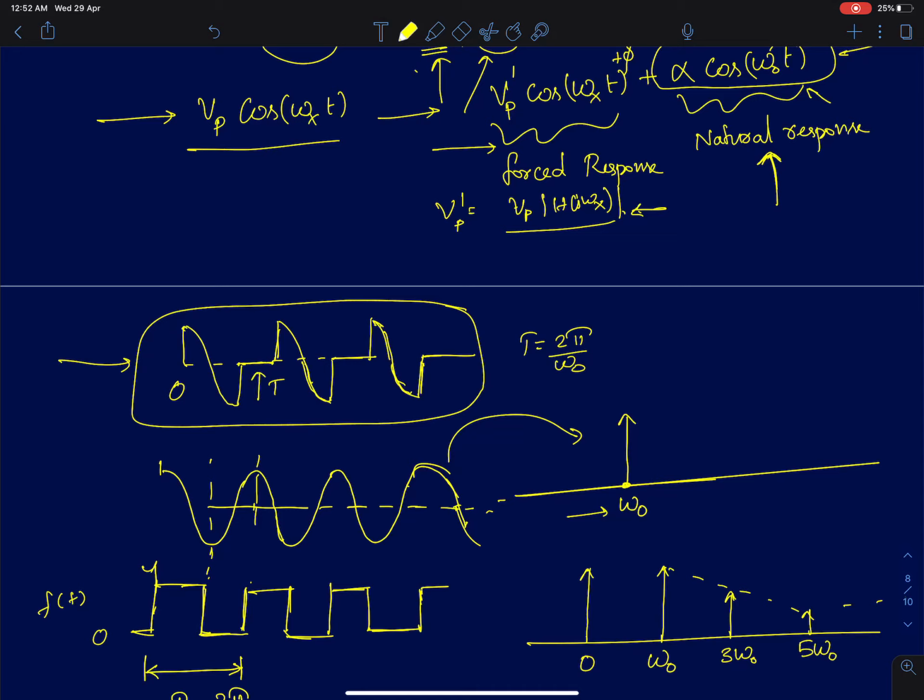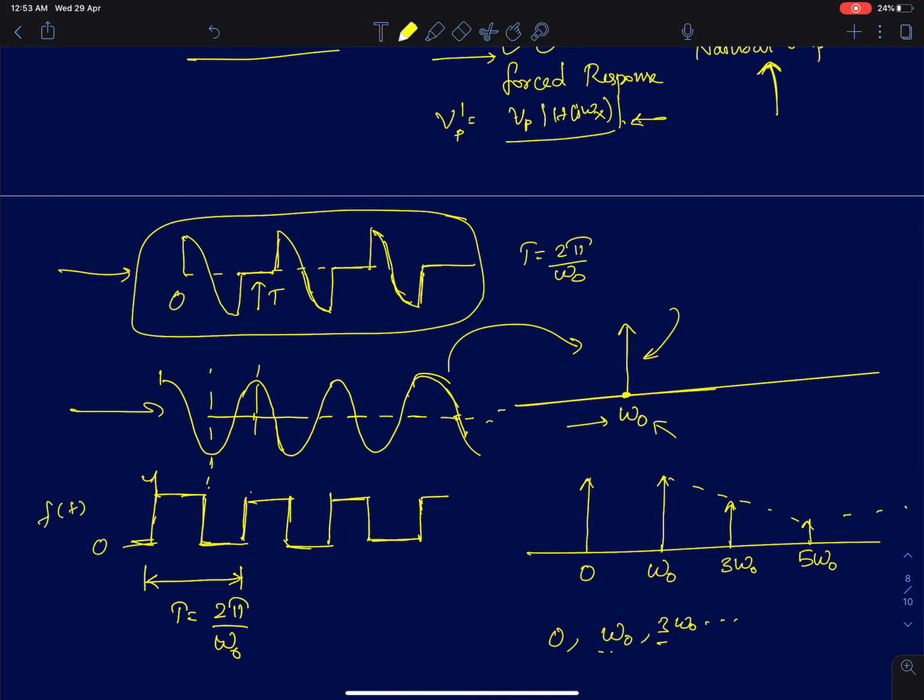Half cycle it is 0, and it's a sine wave for one half cycle. So you can generate that signal by two well-known signals. One is a sine wave, whose Fourier transform is going to be just an impulse at omega naught. And I'll multiply that with a pulse train, a square wave signal with 50% duty cycle. It's going to take two values, which is 0 and 1.